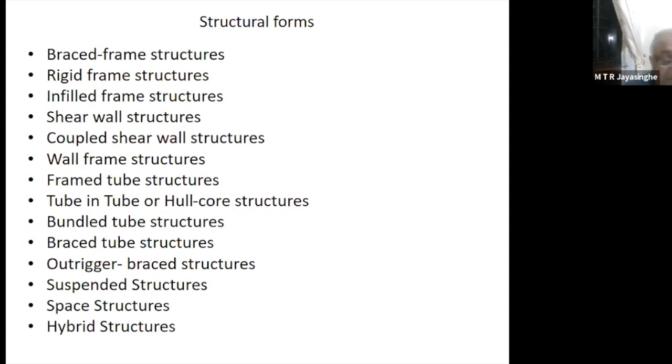But always keep in mind, sound insulation is also important. If you have a very thin slab, sound insulation will not be there. People in the lower floor will always complain. They can't concentrate in their office work because all these people are dragging the tables and chairs and making so much noise. So because of that reason, sound insulation of a slab must be given top priority. And you must consider that factor when you are selecting the slab thickness, especially in the optimized forms.